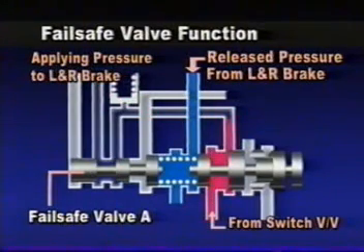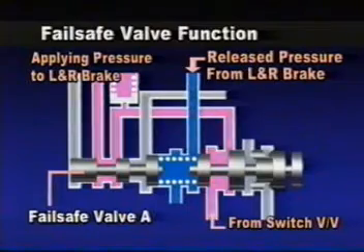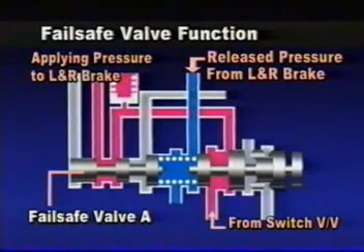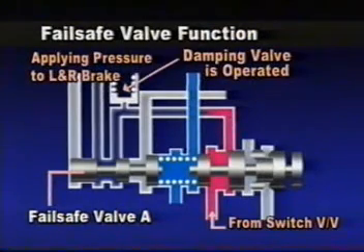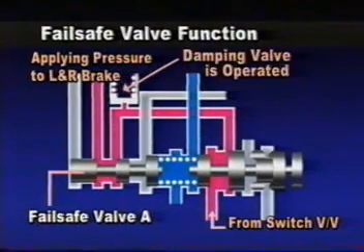Oil is released first and gathered again so that decreasing the shock in into R or P to R shift enhances the smooth shifting. When the oil pressure is supplied again to low and reverse brake, oil pressure is supplied through the damping valve inside valve body to reduce the slight shock one more time.